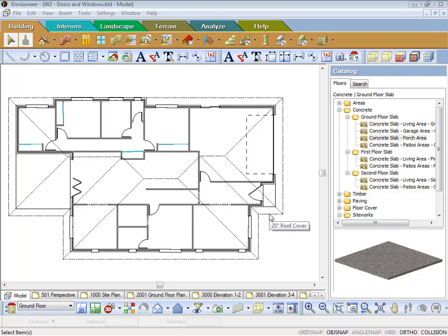In this lesson with a roof, I just want to change the front over the garage from a hip roof to a Dutch gable. Basically, to do that, we can just touch the surface or the edge of the roof, and you'll notice that the arrow or the pitching point over the garage has turned green. That's making that active. The other arrows, as you can see going around the perimeter of the building, are red. So that means I'm just going to work on the front one that is green.